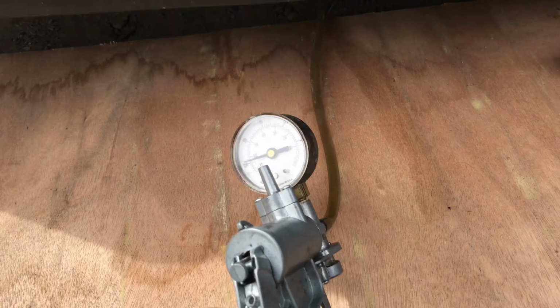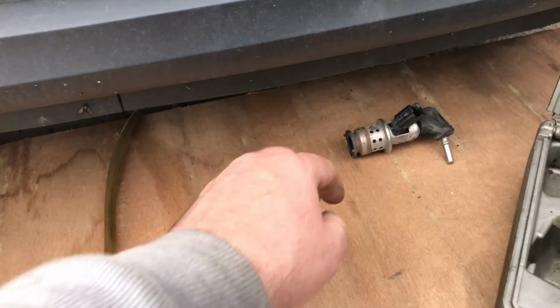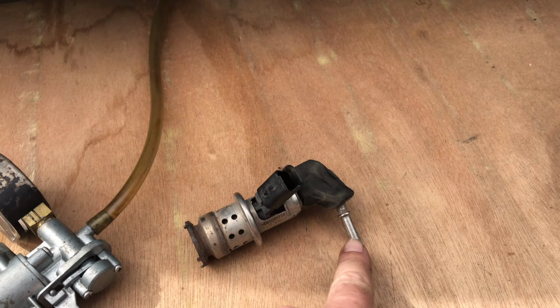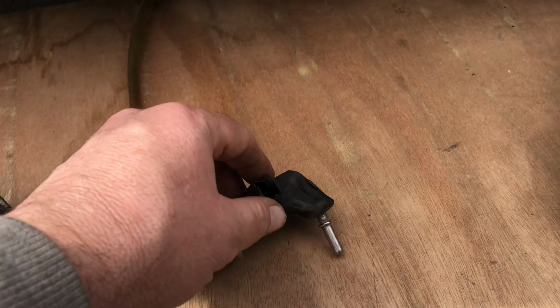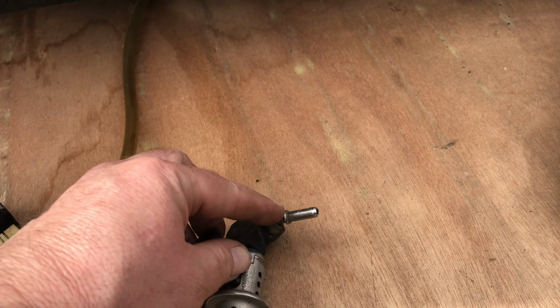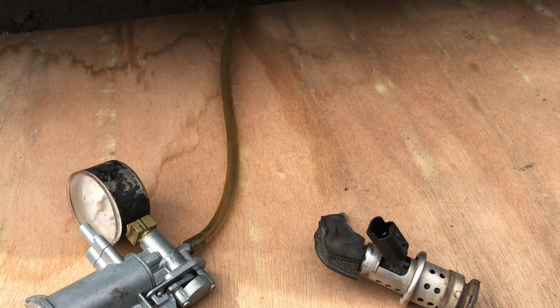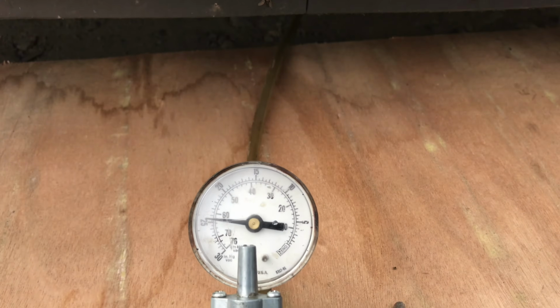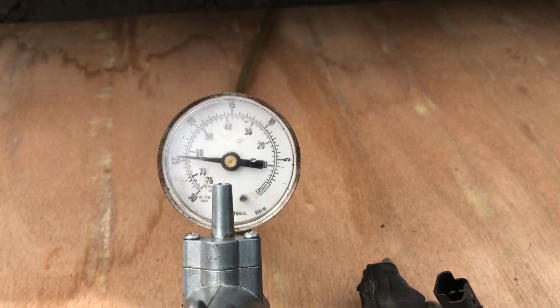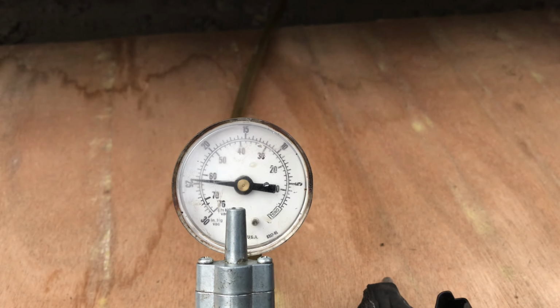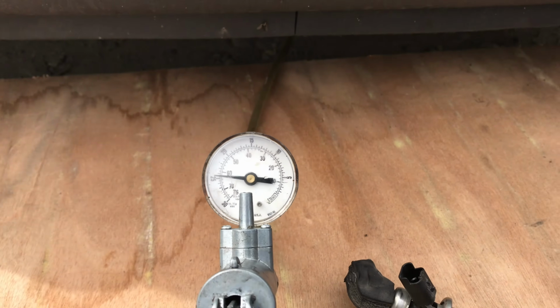Here is I've connected the vacuum gauge into where the quick connect for the urea injector is. I've just made up my own piece from an old one. I've just cut it off. I'll show you it. And what I've done, I've connected it and drawn vacuum. It's been lying like this for the last 10 minutes. So that's holding a good 25 inches of mercury.